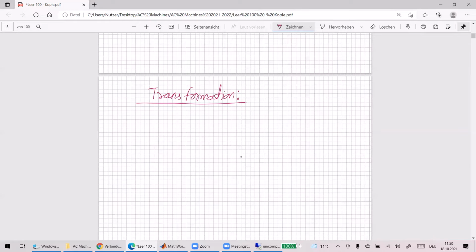When you want to control the magnitude of AC parameters, you can see from the Bode plots, which you will see in the later exercises, that the gain is not perfectly one. So if you want to control AC quantities, you would see that for those frequencies the gain is not perfectly one. It means the reference you give and the actual value you see might not match. If you want to make it one, there is one way: you can use a resonant controller. A resonant controller filters only the particular frequency component, and then you can control over it.